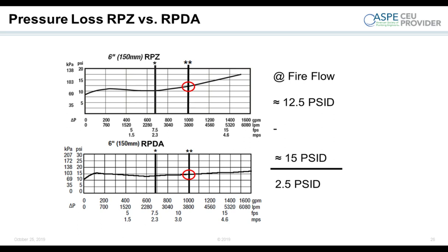So here's where we're getting into the meat of what we're talking about. You notice that in order to drive the first 2 gallons per minute through the main valve in the assembly, we increase the pressure drop across one of the checks. So we need the main valve to open after the bypass, right? We can either decrease the strength of the checks in the bypass, or we can increase it in the main valve. Typically you're going to increase it in the main valve, because that bypass double check or that bypass RP, right, it's already been designed and engineered to be about as low as we can go.